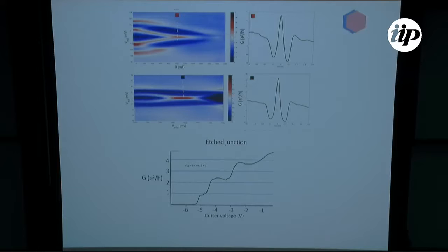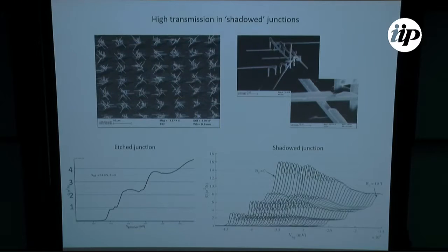and not typically where we form these unintentional dots, as we showed in the Science paper, where we coupled the wire with the dot. When we just have some QPC kind of behavior, then we really get a high zero-bias peak. So there might be something to understand there. Okay. So we're looking at how to improve the junction, because we are really suffering with this etched junction. They form these unintentional dots, and they are kind of different in nature every time we make them, because it comes from this uncontrolled etch where we remove the aluminum.